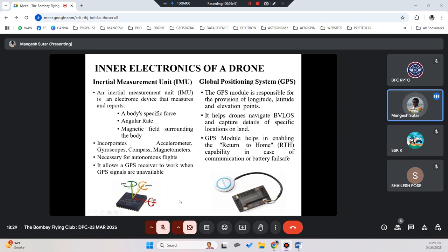It can find how far it has come from the last known signal. So based on IMU data, it can always see at what position it is currently in case there is a GPS failure. In case of GPS failure, it will try to stabilize the drone at that point in time, but there are safety features built in where if there is a GPS failure or GPS module failure, or in case you are not receiving a GPS signal, it will trigger the self fail-safe mechanism.